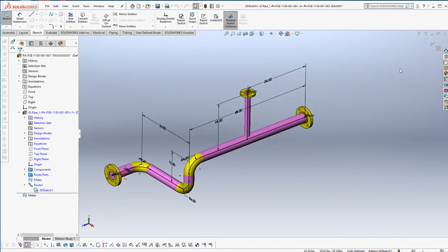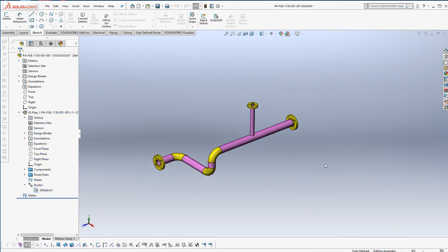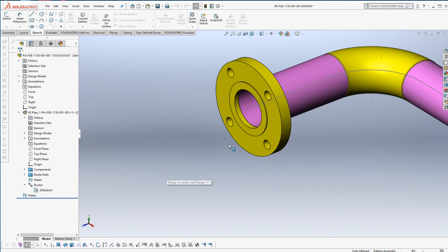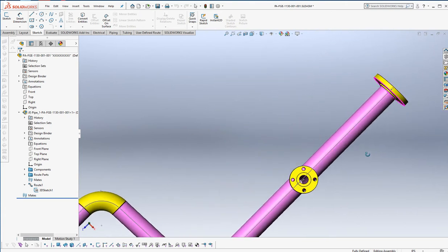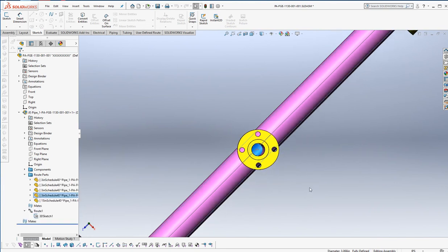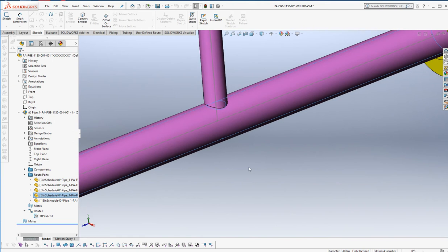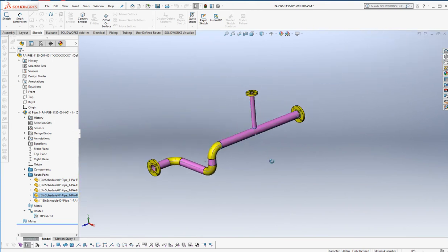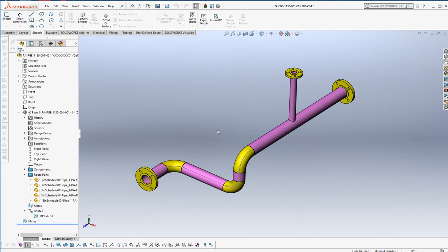Now we'll finish up. We hit check, and then we'll hit check and get back into the main assembly. When you see that, now it's hollow. And if you wish to check down in this tube, what I usually do is I touch the wall in the tube here, and then I look at it, and it kind of tells me, okay, yeah, it's going all the way down to the inner of that tube. And there is a hole there. Always check that so you don't produce the drawing wrong.